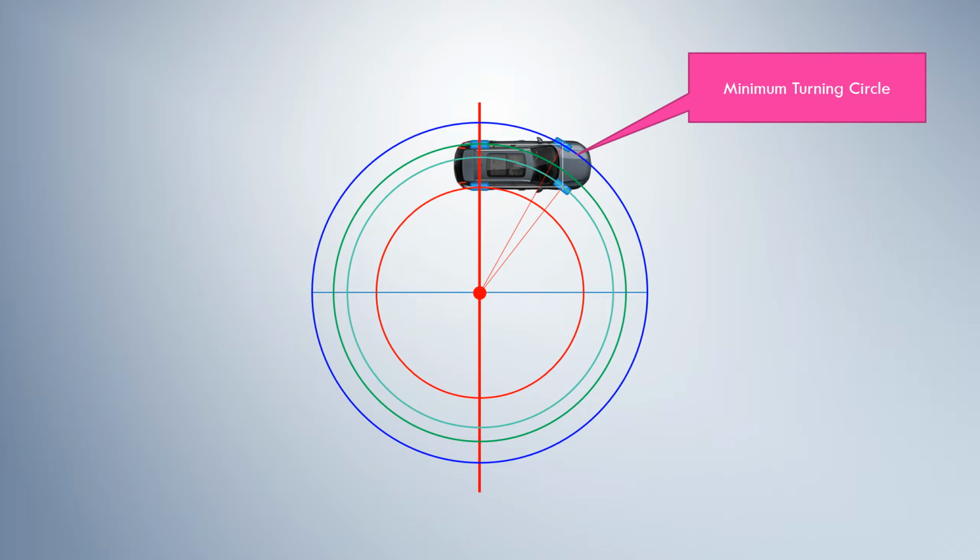4 circles vary depending on the steering angle and the dimensions of wheelbase and tread. When you turn the steering wheel, you see the center point of the circles moves along the extension line of the rear axle. Here, the most important thing we need to know from this video is the center of rotation exists on the extension line of the rear wheel axle. This means, when you move your car, such as parking or turning, you should always consider the position based on the rear wheels.